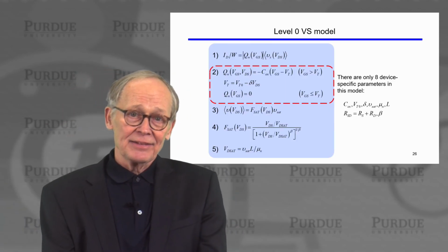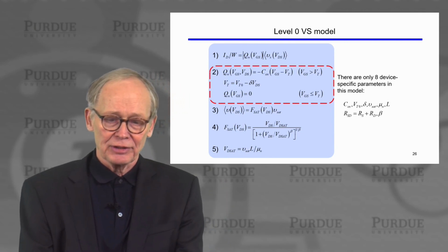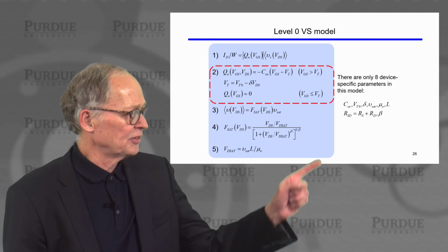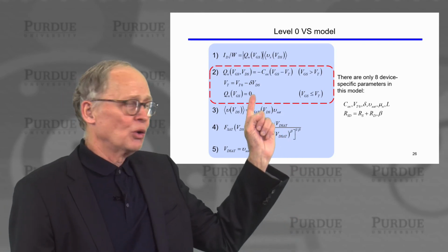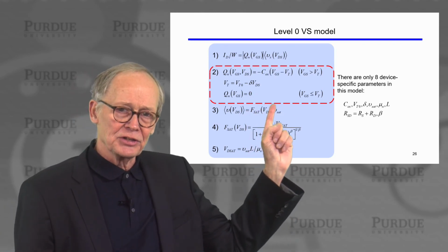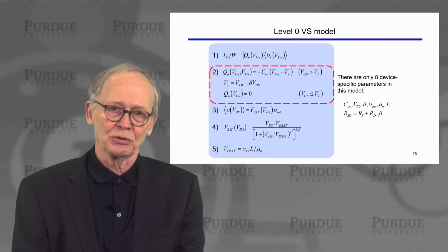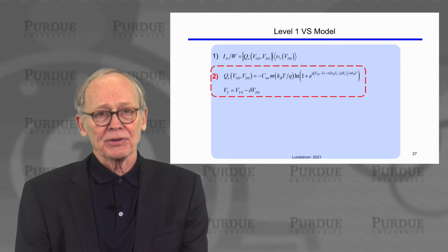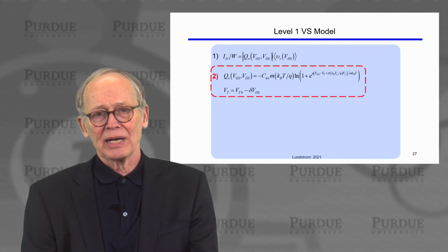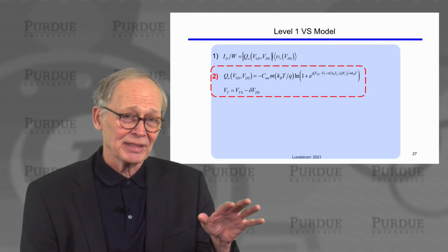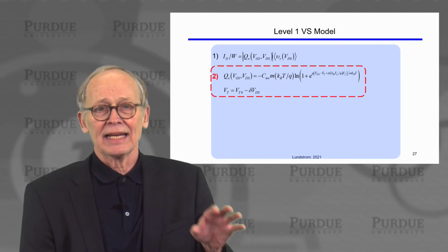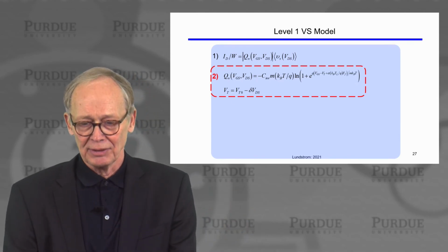Well, to end up Unit 3, we revisited our virtual source model. One of the things that we did is to extend it by no longer assuming that there was no charge when the gate voltage was below threshold. We could extend it with an empirical expression that correctly, or approximately, gives us the right mobile charge below threshold and the correct mobile charge above threshold.